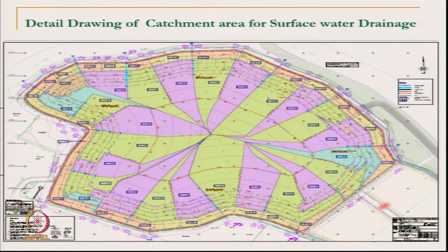This is the way the land was available, and this is the landfill area. And you can see a lot of contours, right? But you can see on this, it has got every area from which the water will be connected, where it is flowing, where are the drains, what are the cross connectivities, and eventually they will reach a toe drain at the bottom. So the details don't stand out, but remember all these are drains which are collecting the water and sending them to a toe drain, which eventually gets connected to the stormwater runoff drain here.